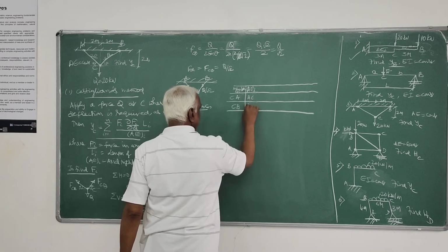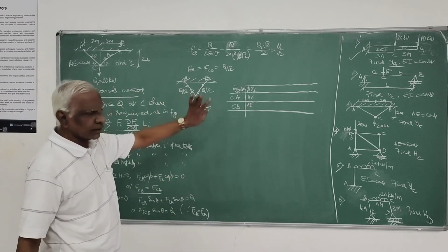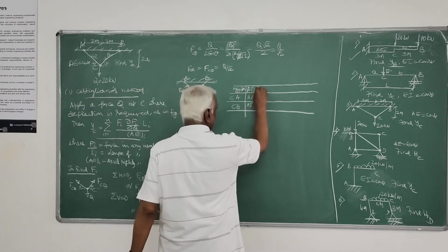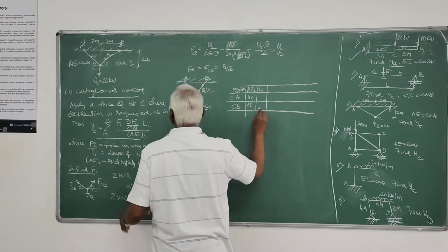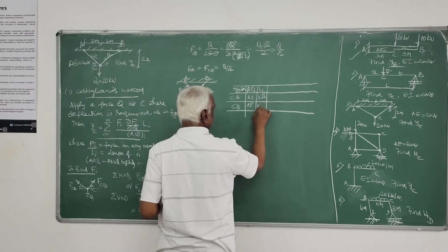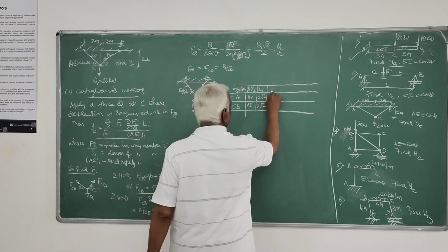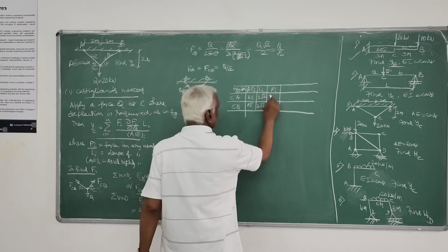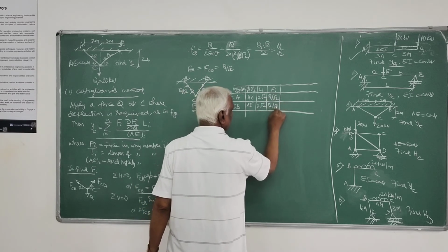AE is constant. If it is valid, you write that value, take the corresponding value, either numerically given values or general values like AE, and Li, the length of the member, that is equal to 2 root 2, that we have determined already, and then F5, that you have determined here, that is Q by root 2, here also it is Q by root 2.